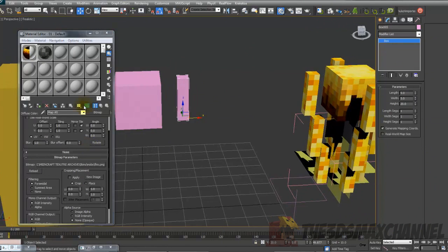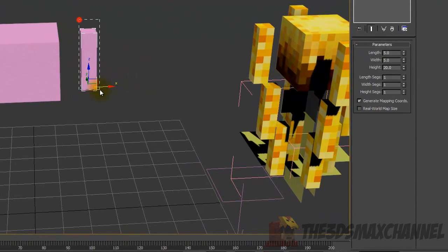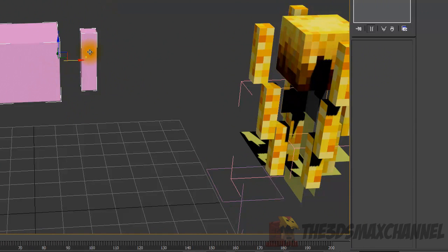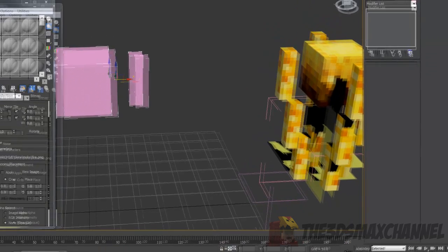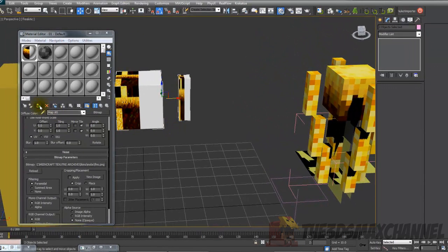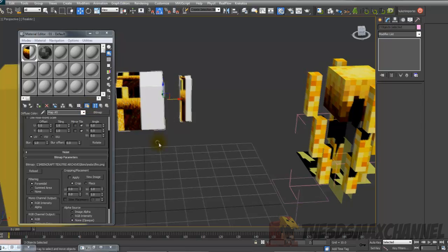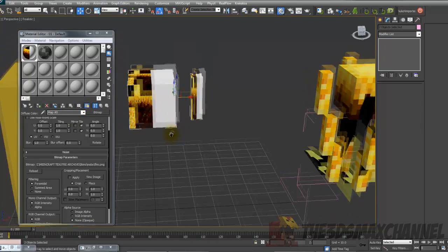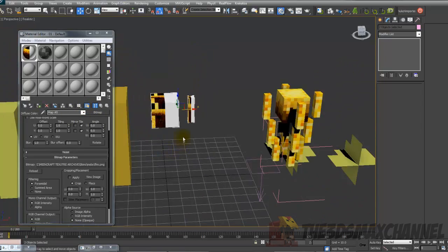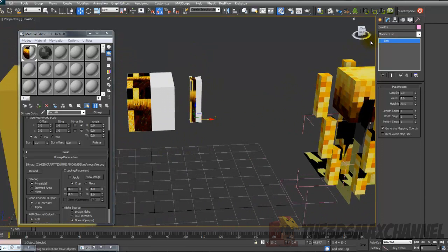When you've done that, with the object selected, so have both the head and the pylon, or whatever you're going to call it, selected, and click assign material to selection, which is the third from the left. So choose that and assign to it. And on the right side, the fourth icon over, show shaded material in viewport. So make sure that's toggled on, so you can see it in the viewport. And then we'll just get on with the UV mapping.